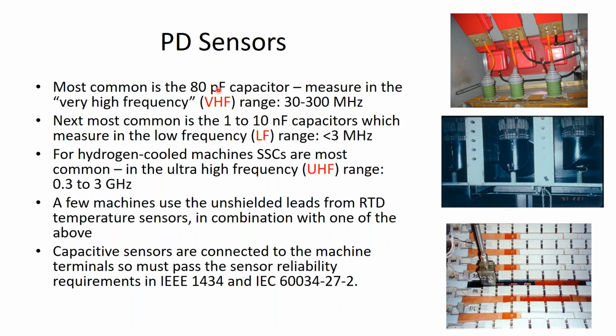And by far the most common sensor is the 80 picofarad capacitor. Just ourselves, we've installed, I think it's close to 80,000 of these capacitors now around the world on 18,000 machines. Okay, and they measure in the VHF frequency range. And you can see these kinds of capacitors here connected to the terminals of a small generator.